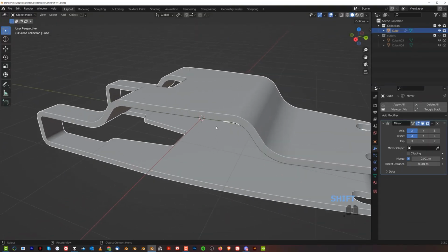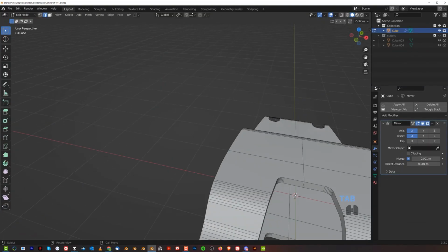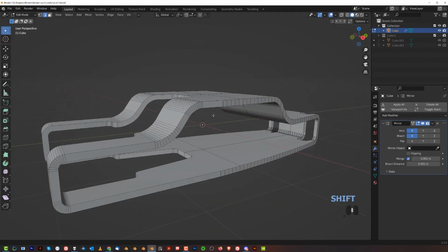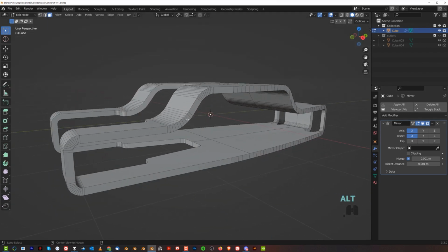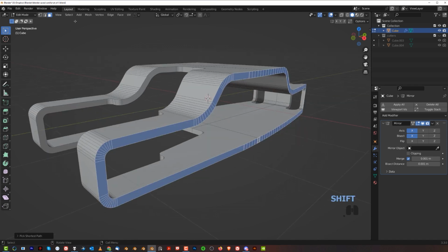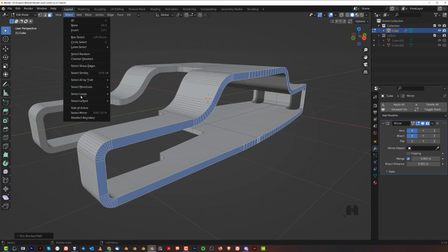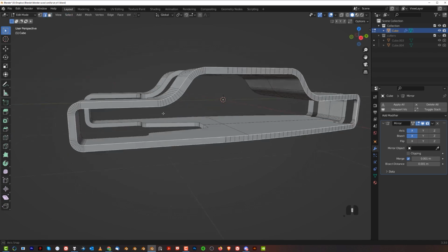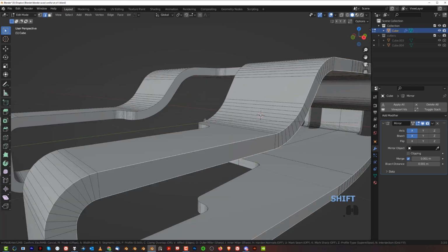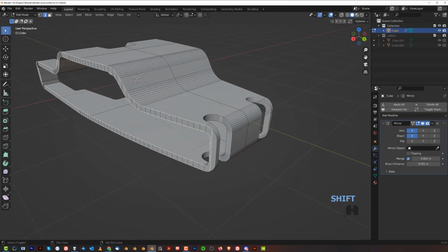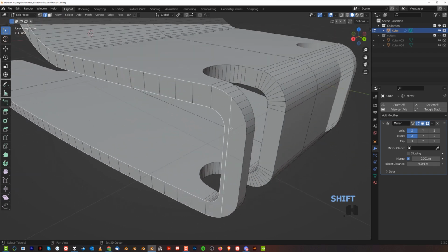So now on top of that, I want to run a chamfer here, okay? So we're going to keep this mirror, so we don't have to do it on every single edge. We're going to alt-click this and shift-alt-click this. It doesn't work. We're just going to hold control and click around this loop of faces here. We're going to go to selection here and go to loops and select boundary loops, which will select these boundary loops, and control B and bevel it. Now you see that doesn't work. And it doesn't work because we have this edge selected, which creates problems.